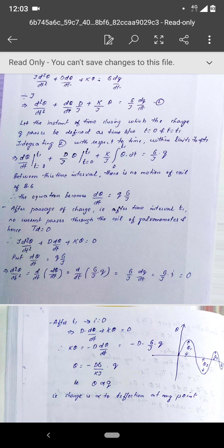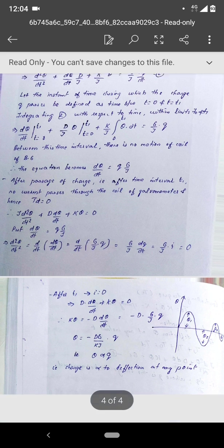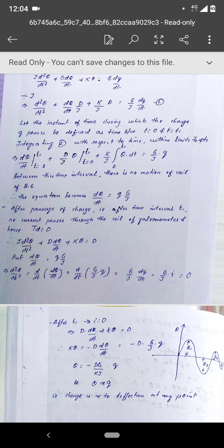You may remember that while we discussed the circuit regarding the BH curve and hysteresis loop, across the ballistic galvanometer we had a key or a switch represented by K. What was the purpose of that switch? I told you that the first swing happening in a galvanometer should be recorded. So here in this figure, that swing is theta 1. So theta 1 should be recorded, and all other swings, maybe theta 2, theta 3, theta 4, can be neglected or simply disregarded.